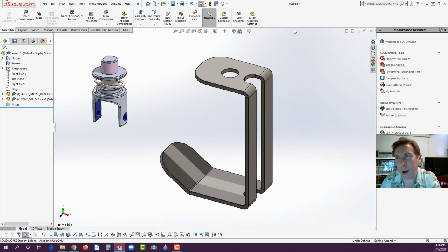All right, so now let's select this one, Filter Faces. And notice the fast key for Filter Faces is X. So later on, if we remember to turn off X, because we might want to select edges, you could just hit X, or you could go back down here and disable it right here. Select all filters, or disable it by turning them all off. Okay, so Filter Faces. Now, if you go over an edge, you can't get it. So just be aware you're going to need to turn this off later on. And X was the key.